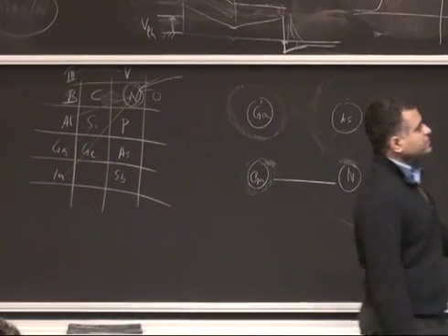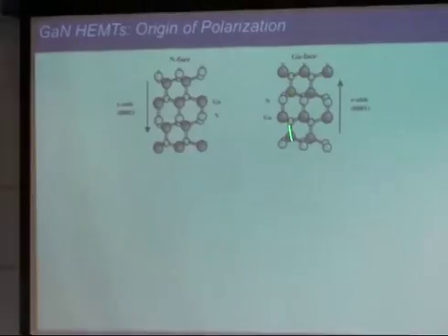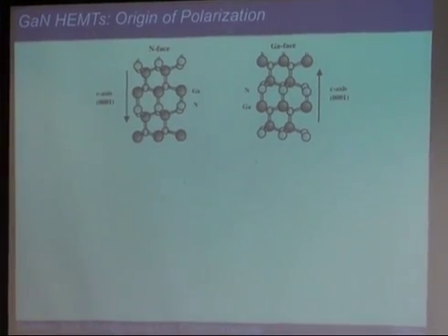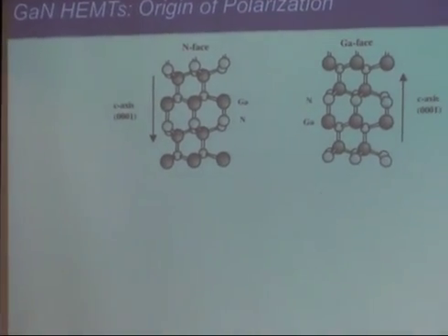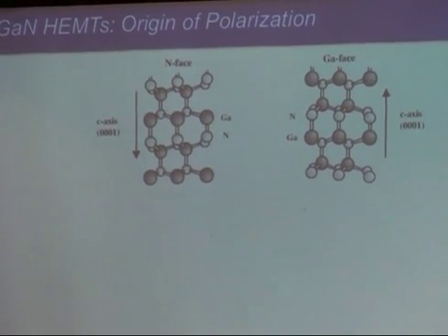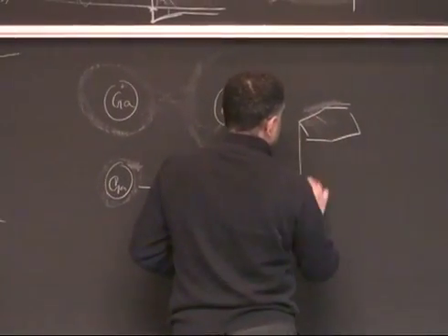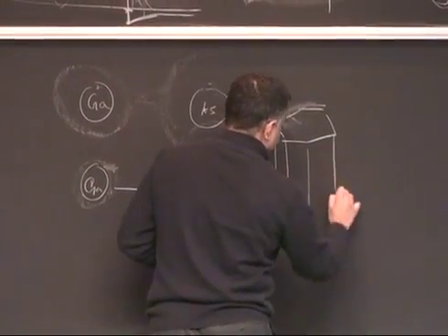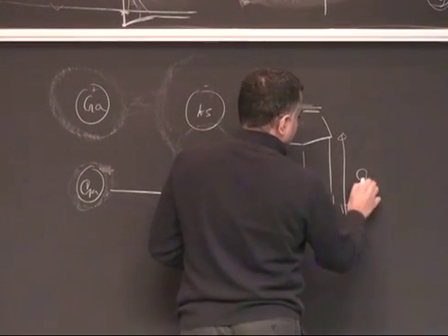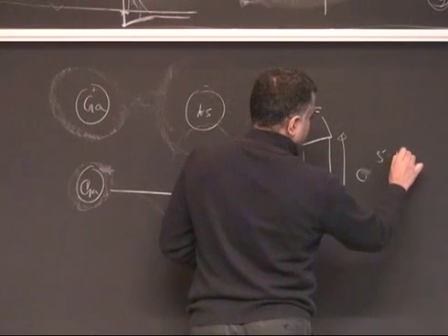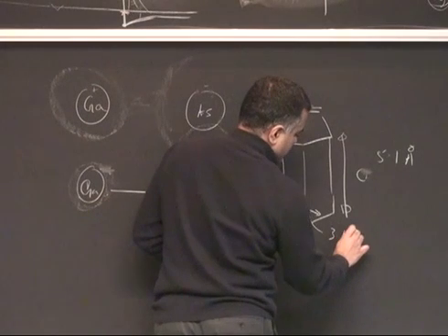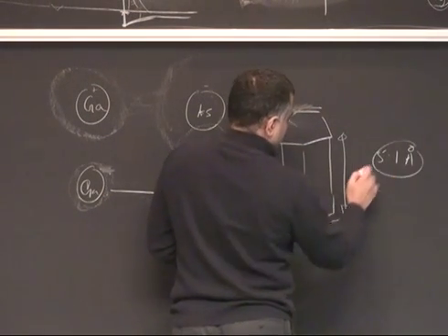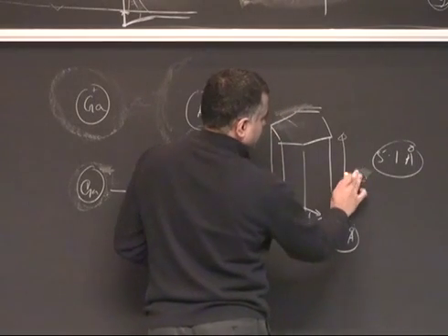You take the crystal of gallium and nitrogen, gallium nitride. Let's look at this one, gallium nitride. It's a crystal, and we're going along a certain axis. This is the uniaxial direction, not cubic, but hexagonal. The geometry of the crystal is hexagonal. This is the c-axis. The lattice constant is about 5.1 angstrom for gallium nitride. Here, the lattice constant in the xy plane is about 3.1 angstrom, or 3 point something, I forget. Okay? And that's called A. And this is C. This is the vertical.